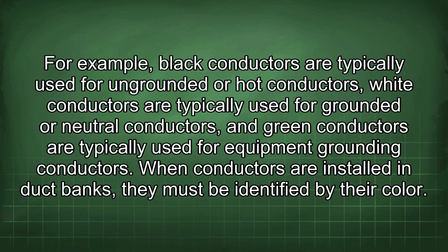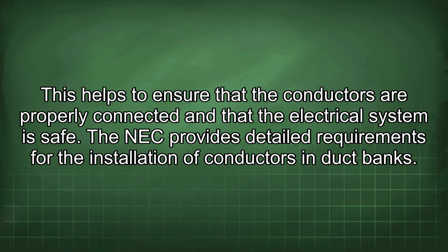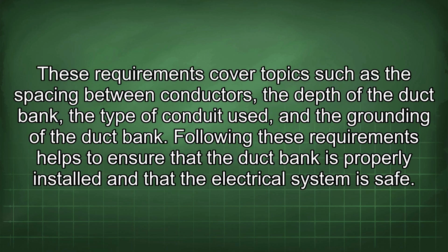When conductors are installed in duct banks, they must be identified by their color. This helps to ensure that the conductors are properly connected and that the electrical system is safe. The NEC provides detailed requirements for the installation of conductors in duct banks. These requirements cover topics such as the spacing between conductors, the depth of the duct bank, the type of conduit used, and the grounding of the duct bank. Following these requirements helps to ensure that the duct bank is properly installed and that the electrical system is safe.